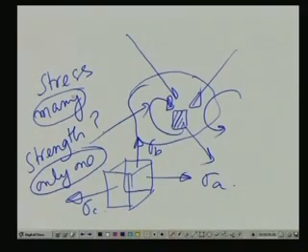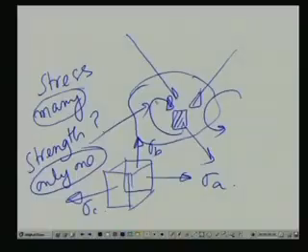So, unlike the simplest situation, here we have to find out the stress at a typical point, or at different points that we primarily talk about as critical points, and then only can we equate it with the strength of the material. The material can be considered by its yield strength or its ultimate strength, so the strength of the material basically comes out to be one.